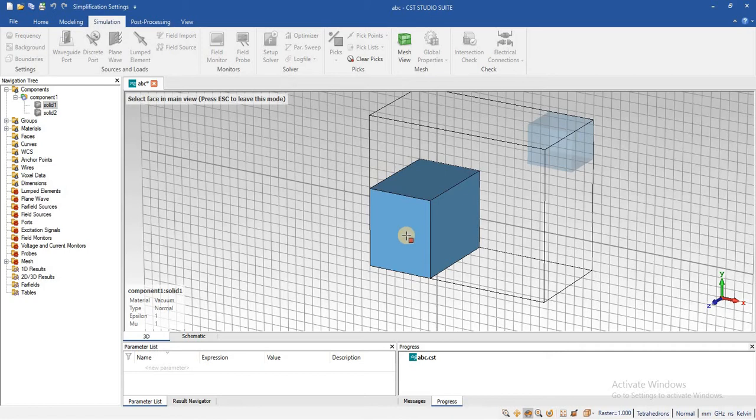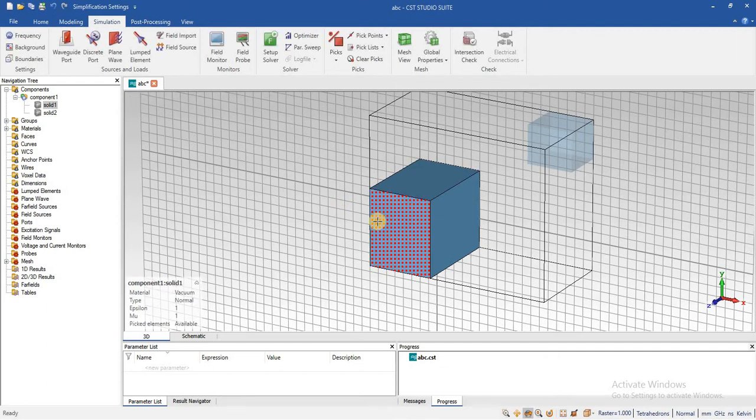First, to pick a face, move on that face. When the color changes, just double click. That face will be selected, and we can draw an object from that face. We can extrude that face, and we will use it in multiple commands with the help of this. We will see that in later lectures.